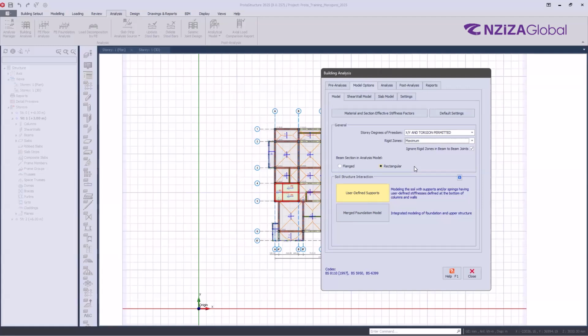If you use maximum, you are considering that the rigidity on site will be perfect, which is not happening on site. That's why the software has provided the 2 other options to reduce the rigidity, which is closer to what is actually on site. So you can choose to reduce this rigidity by 25 or by 50%. It's up to you.